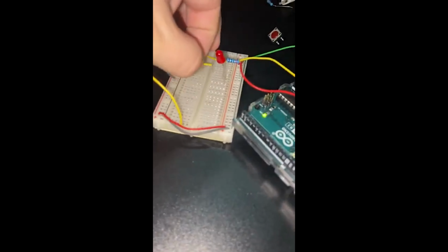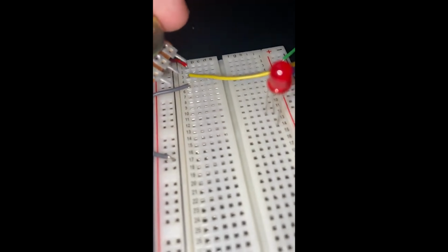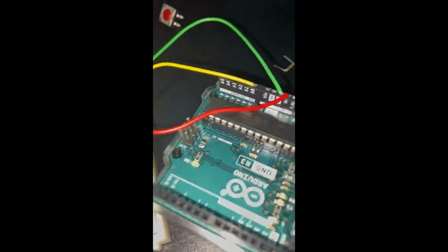So let's hop over here down into the circuit. Now I've already put this code on the Arduino. It's already been flashed. We're going to ignore the LED to start with and just focus on the potentiometer and the serial port. You can see I've got this already set up. It comes from power on one end and ground on the far end. But the pin in the middle is the one that we want to measure, and that's the one connected by this yellow wire to pin A0 on the Arduino.